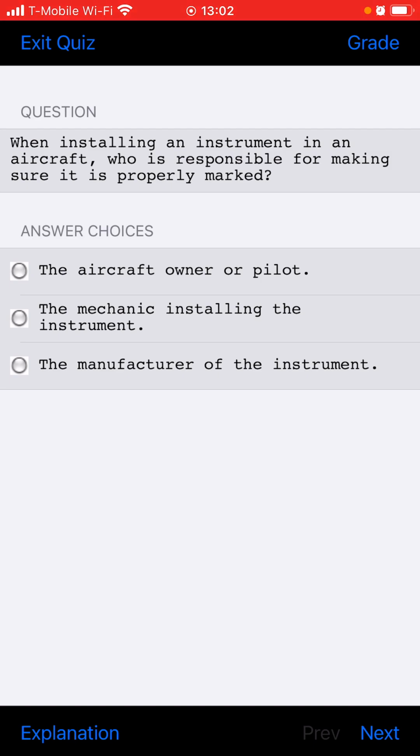Two methods of bleeding brakes. One, a pressure pot can be attached to the bleeder valve, forced back towards the master cylinder. Or the master cylinder can be used, forcing fluid from the reservoir to the brakes. Okay?